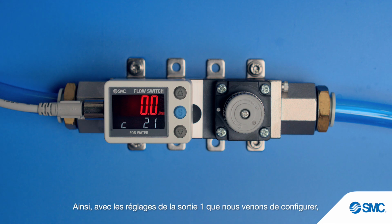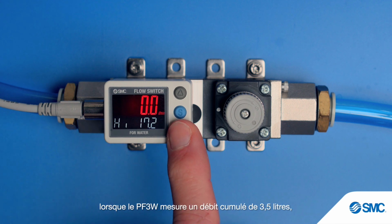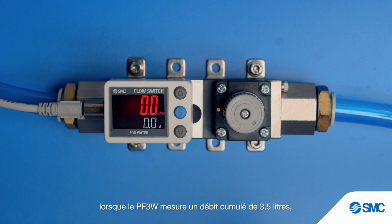So now, with the output 1 settings we've just configured, when the PF3W measures an accumulated 3.5 liters, output 1 goes on and the display turns green. The accumulated value will continue to increase with flow.